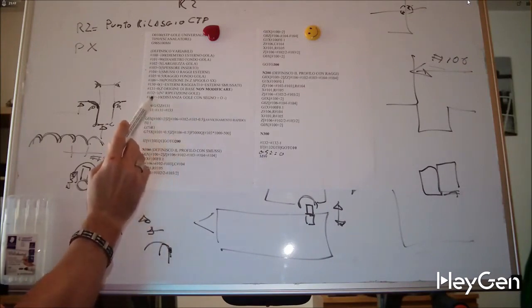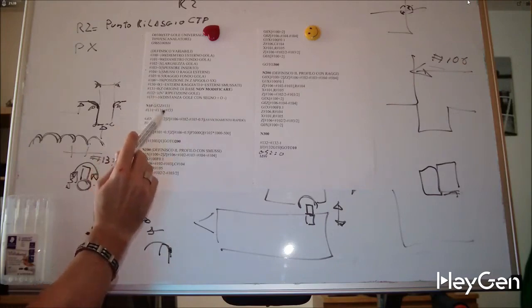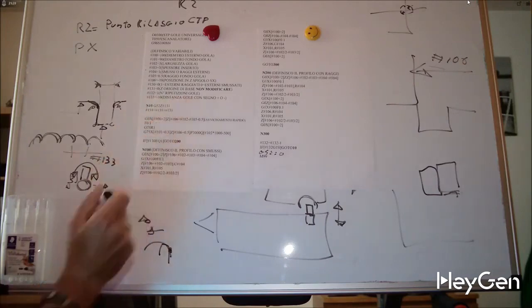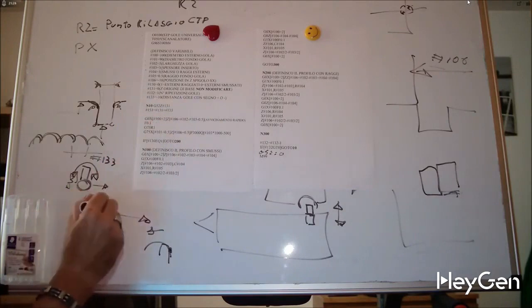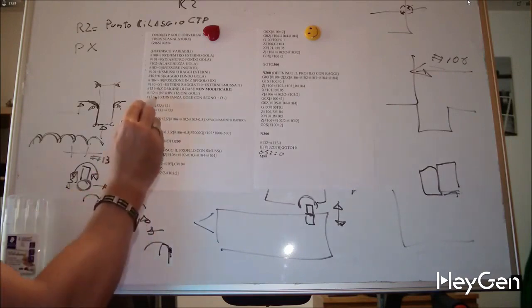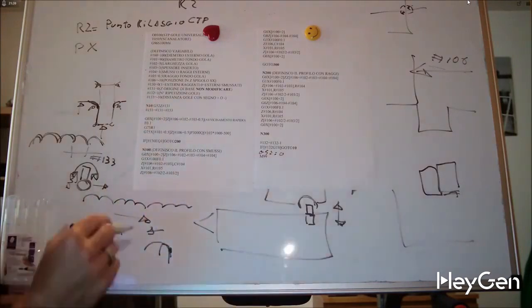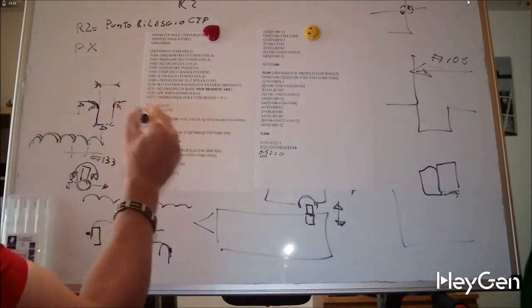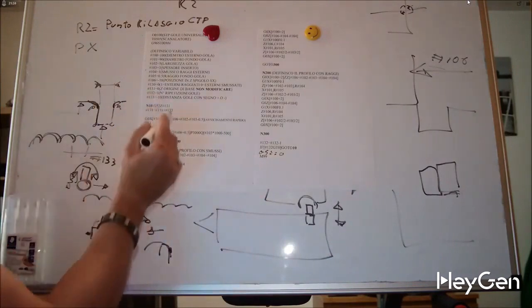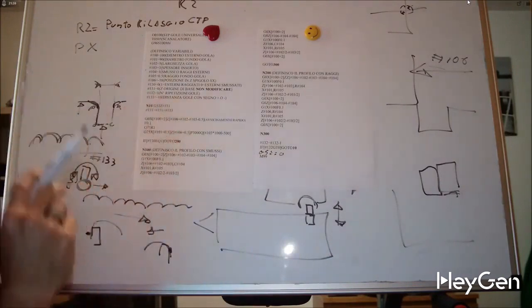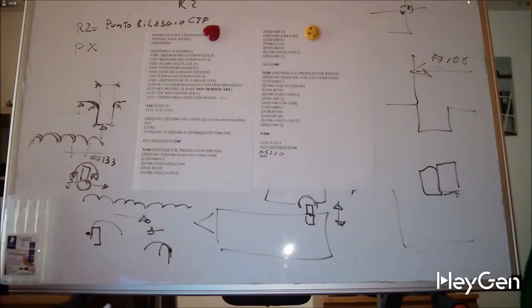Which becomes less for the algebraic formulas, so minus 10 this distance, because I can make the grooves in one direction or the other. So if I didn't put minus here, but put plus, I would have made the grooves from the spindle towards the tailstock, and I'm already shifting my origin. Actually, I'm not shifting the origin, I'm shifting the value that I'll assign the origin instead.